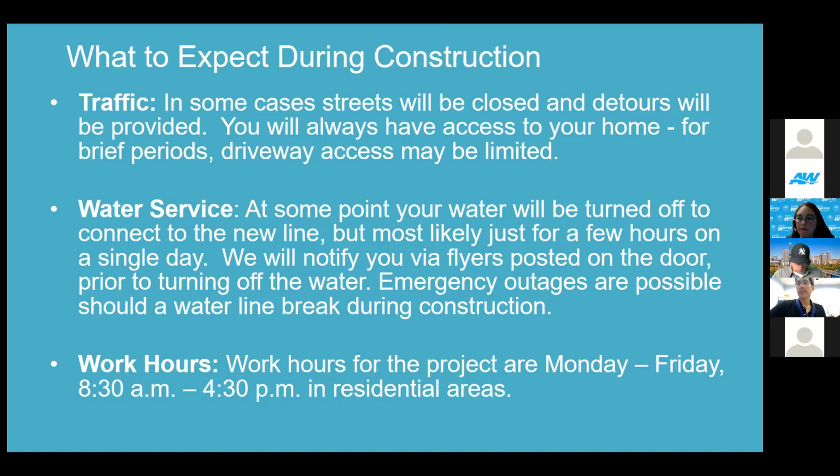And the elevations of those water tanks are such that that's why you're seeing the high pressures in these two neighborhoods. And so what we're doing, with these two pressure reducing valve stations that are going to be located at 290 in Springdale and also 290 in Chimney Hill, is effectively reduce the pressure downstream of those pressure reducing valve stations into both of those neighborhoods.